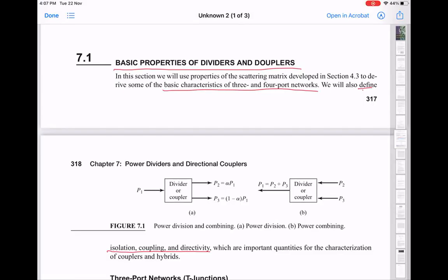So there are some caveats on how to use these power dividers in reverse when your application is for combining the power. And here, I just want to make a point that this is actually very different than what you can do again in low frequency electronics, right? You have all probably built the op-amp summer, which is a very simple device, and it just gives you the sum.